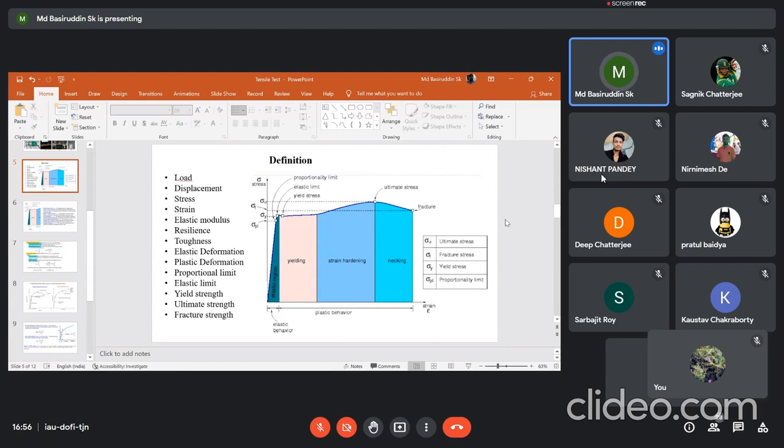In that way, or one thing you can do is take the cross-sectional area at the UTS point, and then take the instantaneous cross-section of the gauge. In that way we can divide it into different points, like true fracture strain, true uniform strain, true local necking strain, something like that. Okay. Those particular equations we will talk about a little bit later.